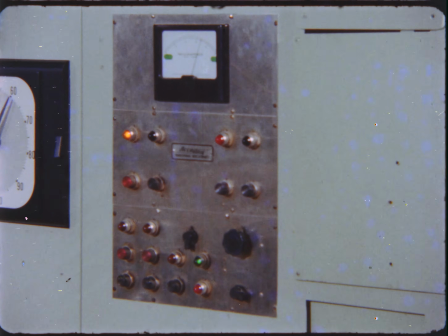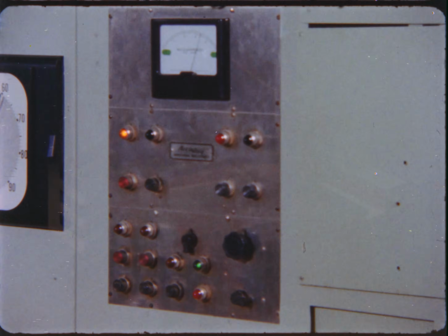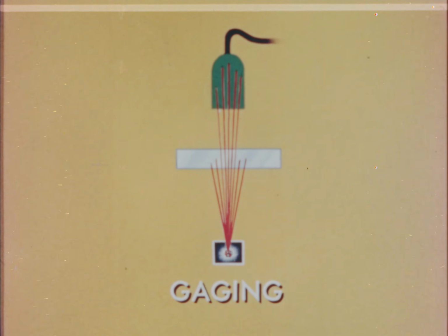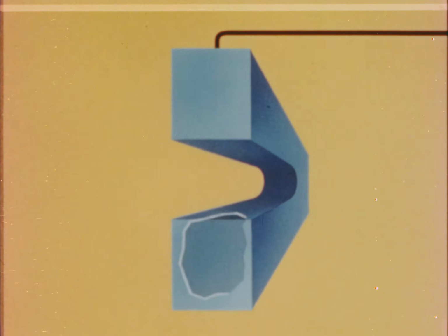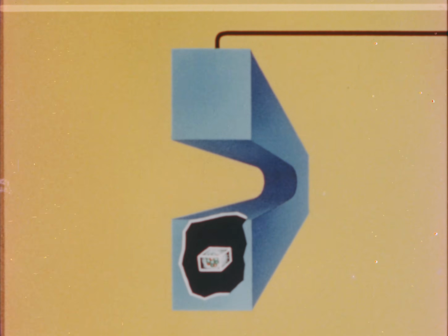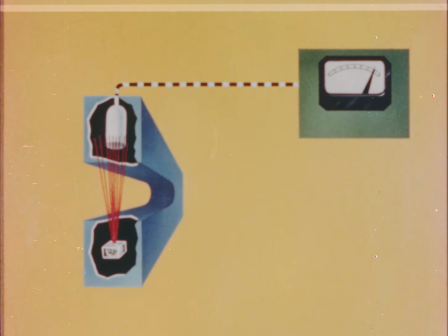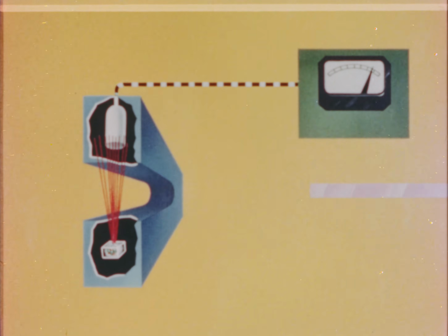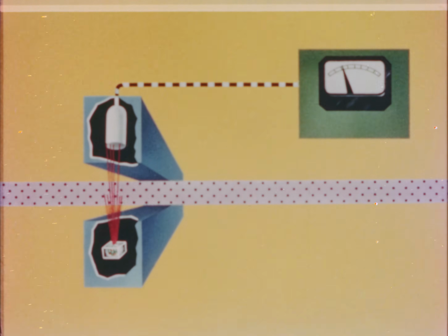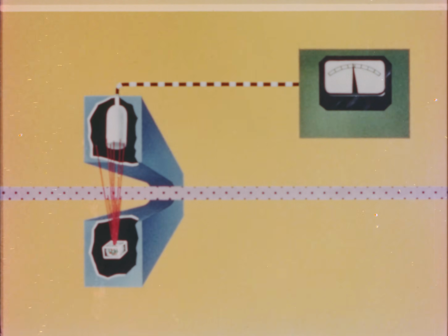To appreciate the safety and efficiency of radioisotopes in industry, let's briefly consider the application. A widespread industrial application of radioisotopes is in gauging systems. As shown here, an encapsulated radioisotope source is positioned opposite a detector. Materials interposed between them absorb or reduce the radiation from the source, depending upon the material's thickness and density. The amount of radiation reaching the detector can be read on a counter or meter. This information may be used to activate automatic controls and, in turn, regulate processing equipment.